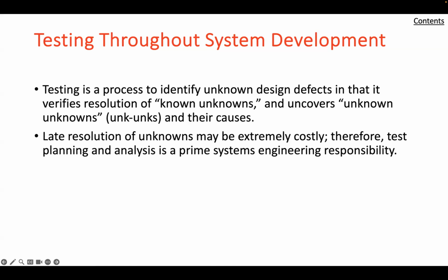This is very often a system level rather than a component level decision, especially if the performance of the element can have a system impact. If the unknowns are largely in the functional behavior of the element, then a computational model or a simulation is indicated. If, on the other hand, the unknowns are concerned with the material aspects, an experimental model is required.